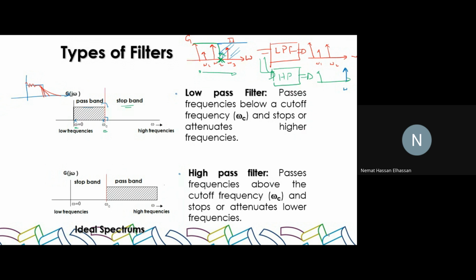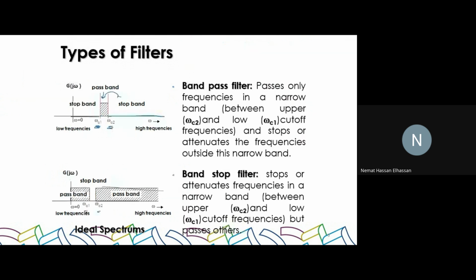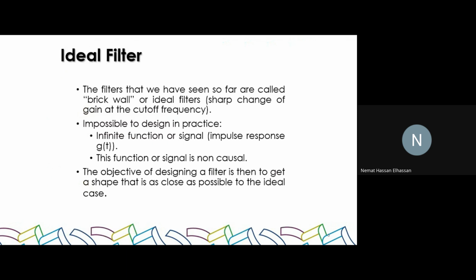Solutions that make this transition sharper tend to create a rippled gain. So it becomes a trade-off. It becomes a matter of getting to that exact spot where you get acceptable ripple and acceptable transition roll-off. Does that make sense? We will see how that applies in design and mathematically in a moment, but let's just get the concept. So these are ideal filters.